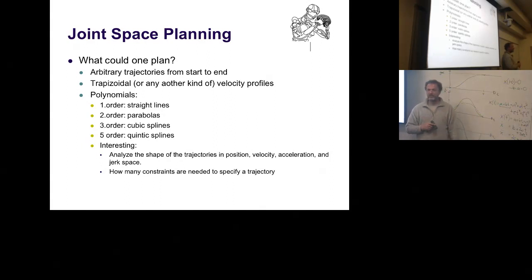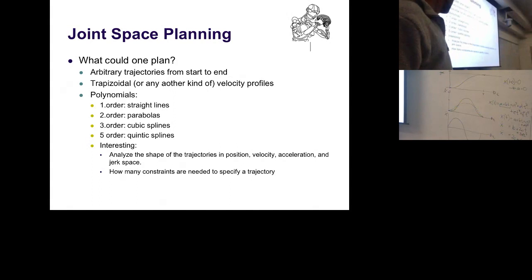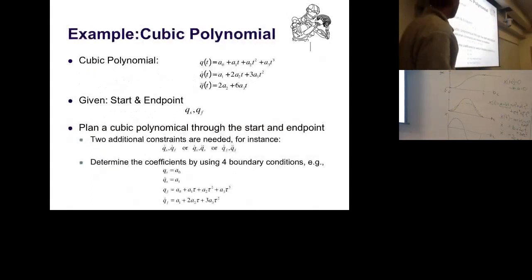And so there are certain trade-offs where you start thinking about what is good or not. What can happen with the fifth order polynomial if you do a very short time movement is massive accelerations and decelerations, which you can hardly realize. It all looks great on a big time scale, but the moment you go into tricky situations, where you need to do a small corrective movement of 100 milliseconds, you get very high acceleration spikes, which may kill you and create a lot of vibrations in your robot, and suddenly the stuff is not good anymore.